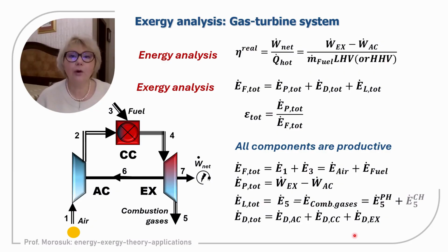For the exergy analysis, we always should discuss state zero. We know that the first topic to discuss for the application of exergy analysis is where to select state zero. For the open cycle gas turbine system, the answer is quite obvious, because air is coming from the environment. Definitely the temperature and pressure of air coming from the environment will be state zero for exergy analysis.